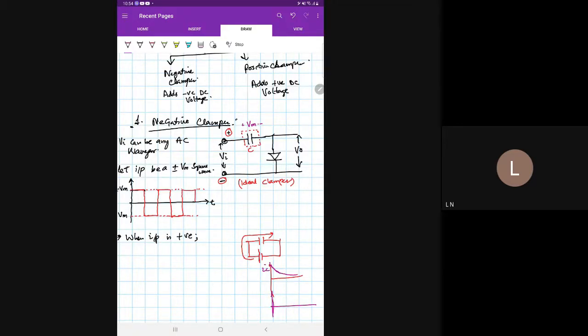Because the capacitor is discharged, the capacitor has no charge. So what will be the voltage developed across the parallel plates of the capacitor? It will be zero. Initially the capacitor is not charged, it is discharged, it is uncharged. Now see, the voltage across the capacitor, which is VC, in this case will be initially zero. But as the current flows inside the capacitor, as the charge flows inside the capacitor, its voltage will develop. So VC will develop and finally it will be constant.